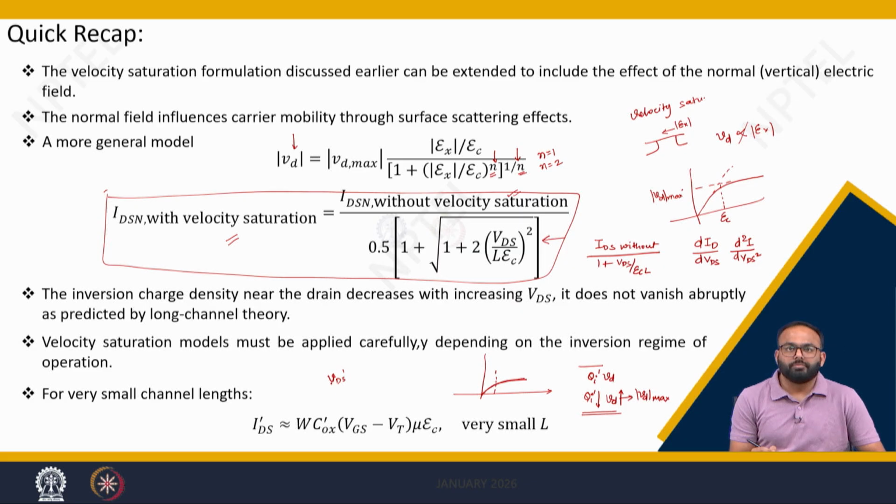The third thing we calculated is that the spacing between the current curves is no longer dependent on Vgs minus Vt whole square, whereas the current was dependent on Vgs minus Vt. It means the spacing between the curves is linearly dependent, not quadratically dependent.